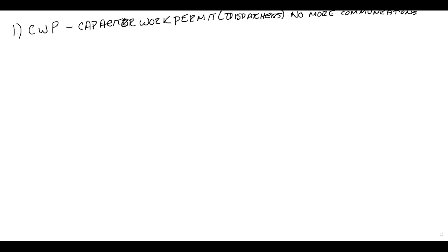And you can do that by pole number, or you can look in the control box and there's an address for the capacitor bank itself. Okay. Two, send open signal. Now the dispatchers, they've cut off automation, but they can still send open and close signals manually from the dispatch center.